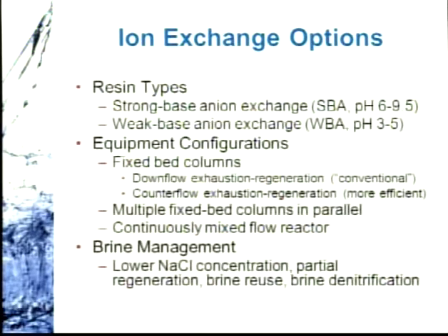These resins are typically applied in fixed bed columns, so pressure vessels, downflow, exhaustion and regeneration, where you've got the water flow for treatment and then the brine flow for regeneration. If those both go downflow, we call that co-flow regeneration or co-regeneration, that's a conventional approach.